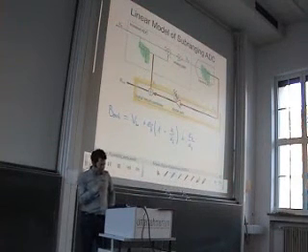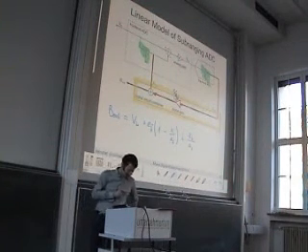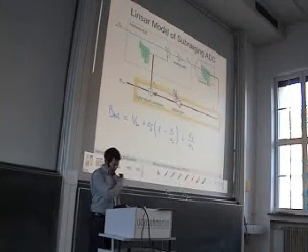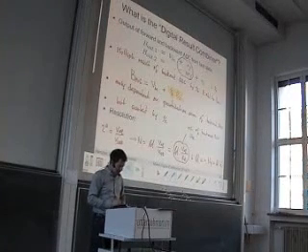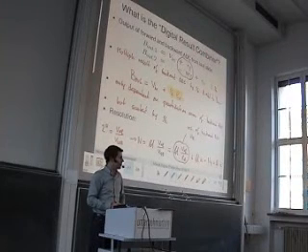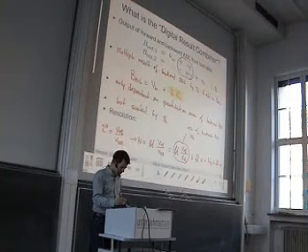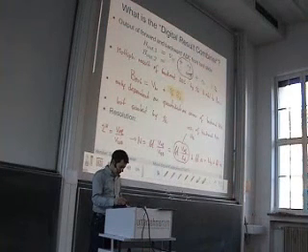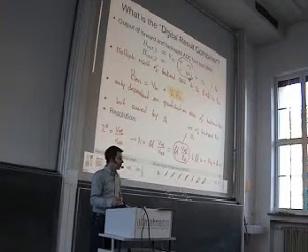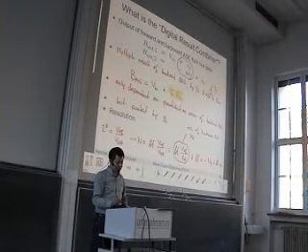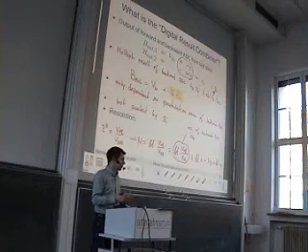So if you look at this equation, then you might ask, well, on the previous slide, he told us that we get rid of the quantization error of the first stage completely. This is what we saw here, that this EF and the A times EF in the second equation compensates because I multiply it with A and then it compensates.